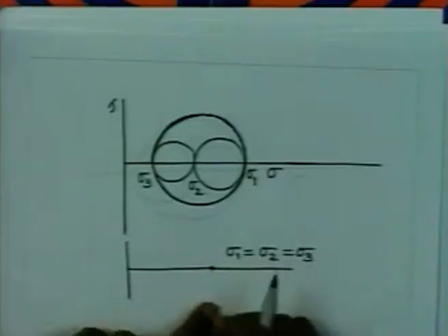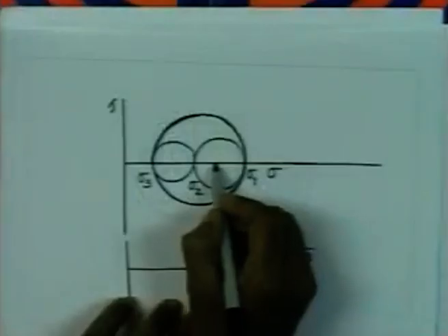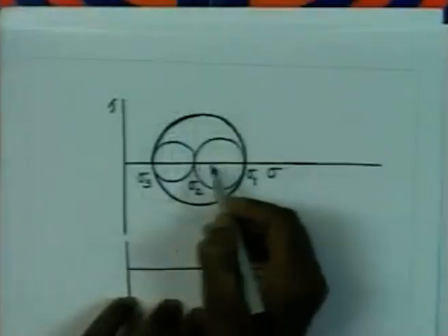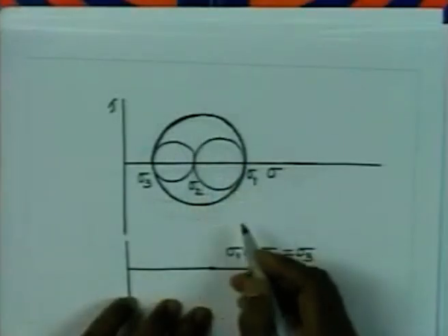any 3 directions can be taken as principal directions, and it is good to consider 3 orthogonal directions, mutually orthogonal directions as the principal directions. Now, other important point that I would like you to also note, that on this Mohr circle diagram, the direction sigma 1 is given by this radial direction, sigma 2 is given by this radial direction, and they are 180 degree apart.